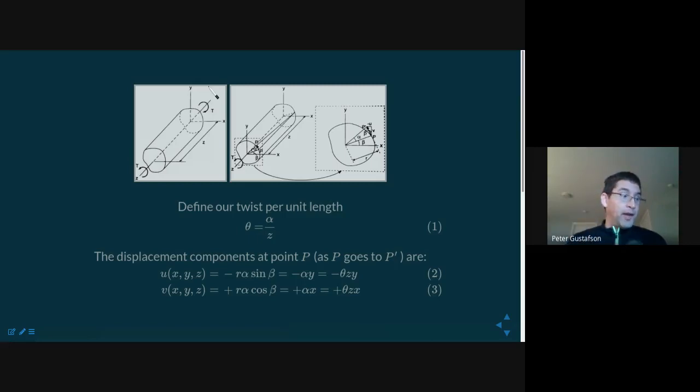What happens when something torques? Okay, when it shears. If you go back to elasticity theory, the very first couple of lectures of the semester, I said that normal strains are extensional strains. They can change volume. They certainly change length. Whereas shear strains are angular changes.